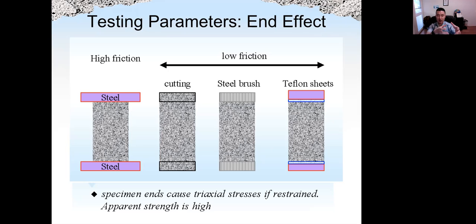remember the horizontal direction, the concrete will try to expand, because concrete has a Poisson's ratio. You compress in the vertical direction, in the horizontal direction it will expand around 20%. However, the steel will provide friction or restrain the expansion in the horizontal direction, so that will kind of prevent concrete from cracking. Okay, I think I need to use the iPad again.